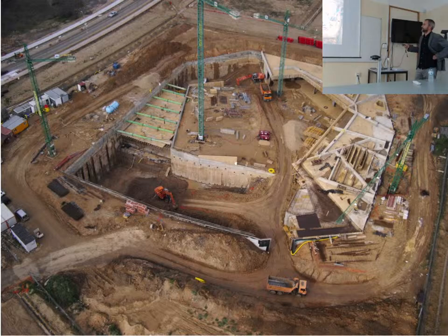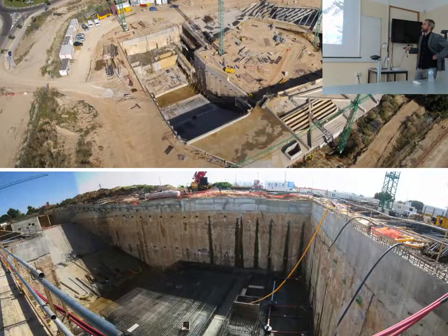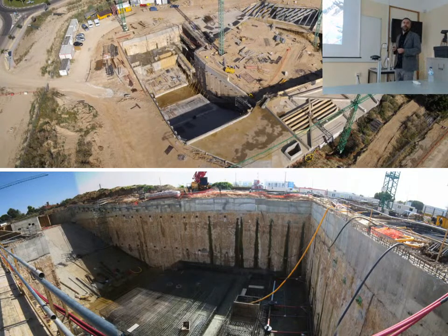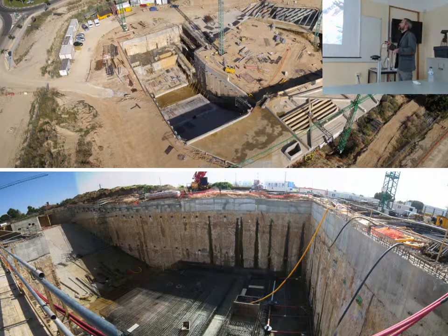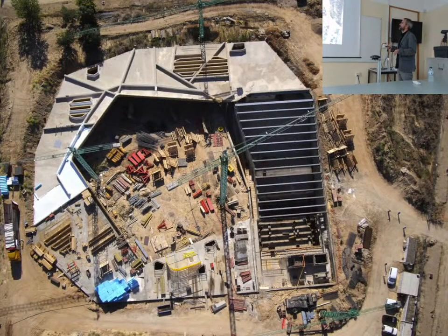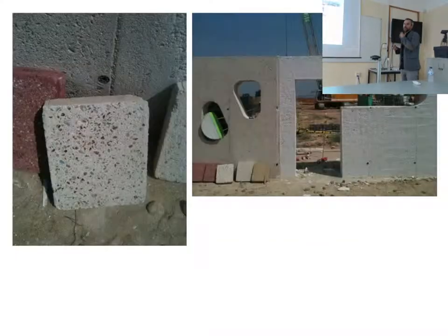Then we have the main auditorium, the secondary auditorium, and the space for all the installations. The main auditorium was quite a big hall. We have water there, which was quite difficult, so we have to provide a quite thick slab, rough foundation below. And we have a big void here because of the main stage. We don't have any floors in between. You see here the secondary auditorium, and the main auditorium was all a composite structure, with steel beams connected to a steel deck on top. And then I'm going to focus now on the box.